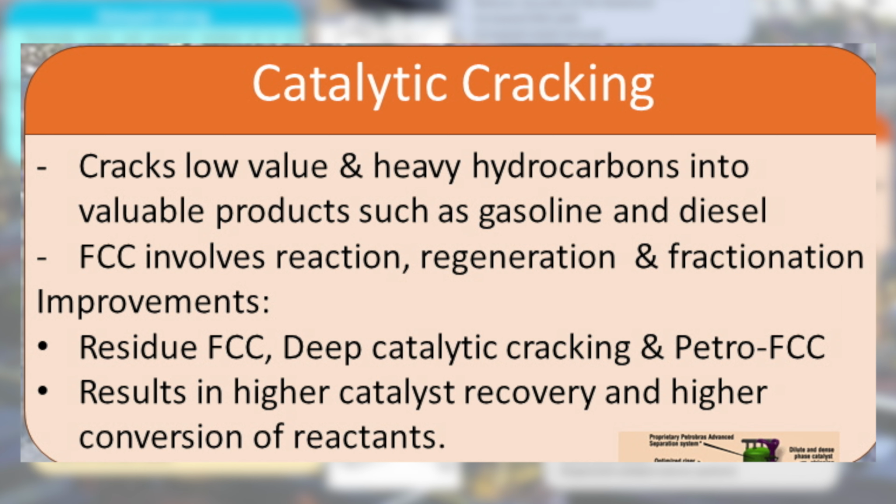to their heavier counterparts. The main reaction involved in the catalytic cracking process is the cracking of long-chain hydrocarbon. Fluid catalytic cracking cracks low-value, high molecular weight hydrocarbons to more valuable products such as gasoline and diesel. Main reactions involved are cracking, where heavy hydrocarbons are cracked into lighter hydrocarbons, and dehydrogenation, where hydrogens are removed. Main feedstocks are vacuum gas oil and hydrocracker bottoms.